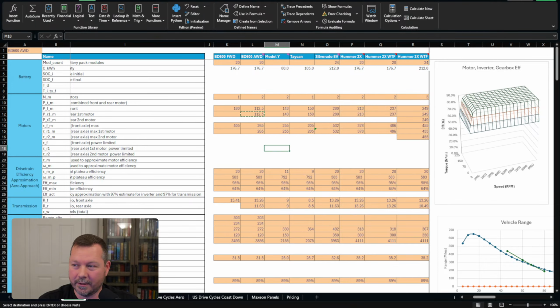And that's another thing too with this build on the camper: there's no plans to make any kind of modifications to the van itself. So the charging would be you literally plug your charger into the van through some kind of pass-through port. So you're not tying into the charging, you're not tricking the battery. If you connect into the battery, you're going to mess with the battery management system, the range calculations. You could overcharge, you could mess up all kinds of things. So the vehicle needs to know from its designed communication port what's coming in and going out so that it can manage everything. So yeah, no modifications to the van except for cosmetic stuff.